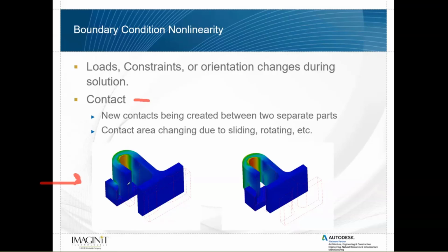You can see at the beginning of the analysis, it starts to slide into the buckle and you get contact where the snap is being pushed back. And then at the end of the analysis, it starts to push through the buckle and the load path and the stress change to be more along the middle of the buckle as it starts to snap through that fitting. This is something you can't do with linear static analysis because the solver wouldn't be able to solve that half-inch displacement all at once. You need to run it through nonlinear static so that it can calculate all this new contact that's occurring at every single increment as this buckle snaps through the fitting there.